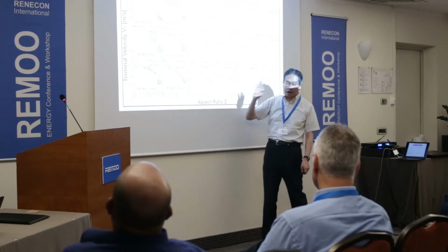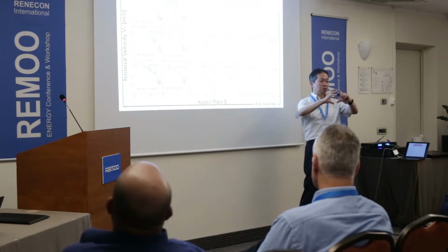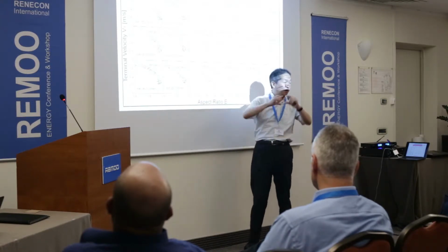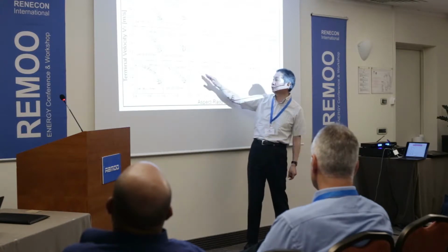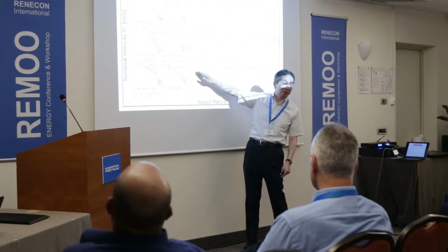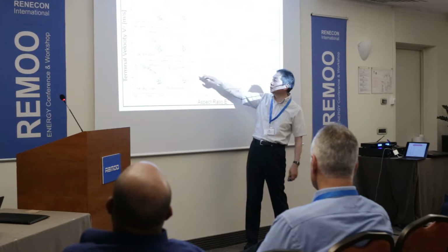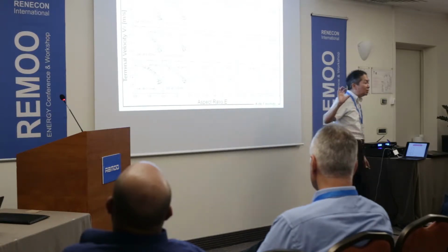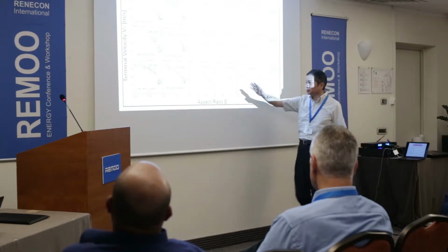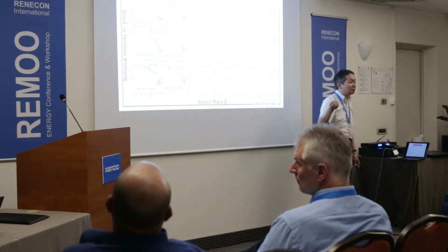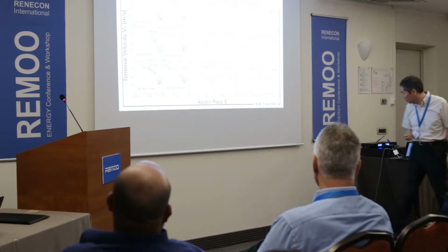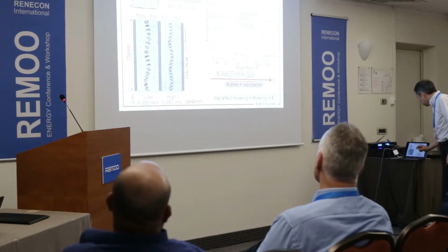Aspect ratio 1 is equal to a spherical bubble, and a low value means highly deformed. So the highly deformed aspect ratio gives you a higher rising velocity. And this equation gives really nice agreement with measured data, so we actually have to take into account bubble shape if we want to obtain really good agreement with the measured data.